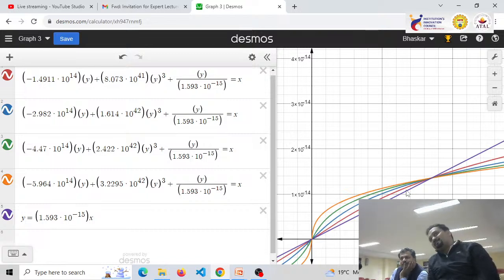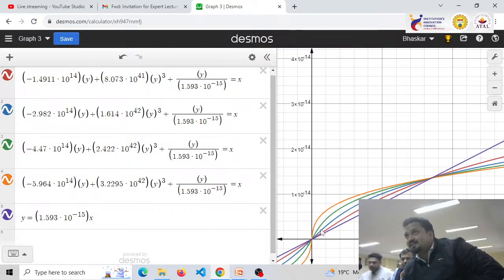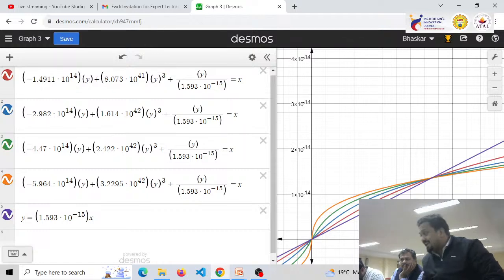So now you can see the red curve. The red curve signifies that here the slope is not negative, it's positive. And if you see properly, this is nothing but charge versus voltage, correct? On the y-axis I have charge and on the x-axis I have voltage. Capacitance is nothing but Q by V. So Q equals CV, so capacitance equals dQ by dV. So this capacitance is higher as compared to this.